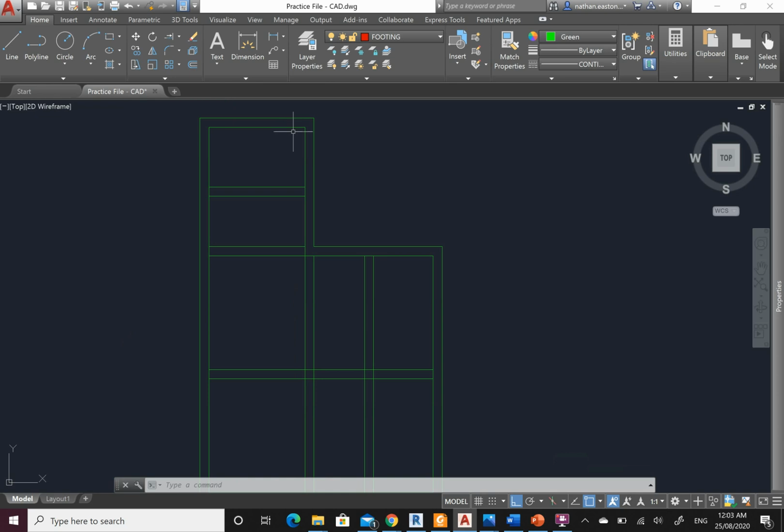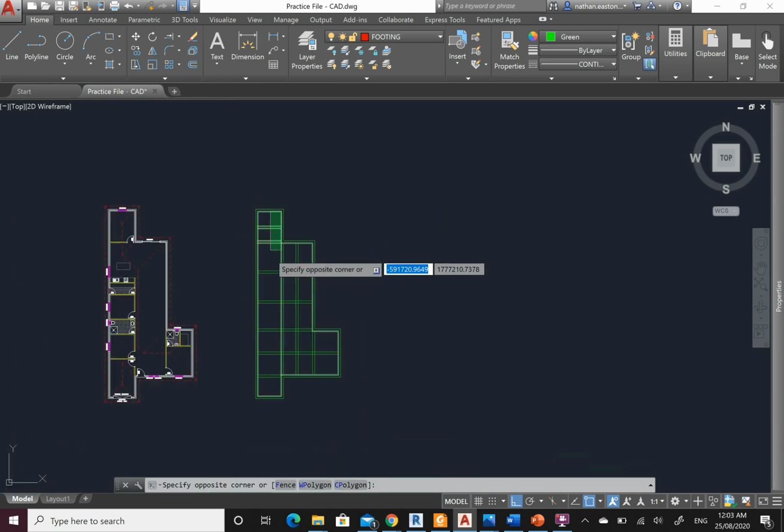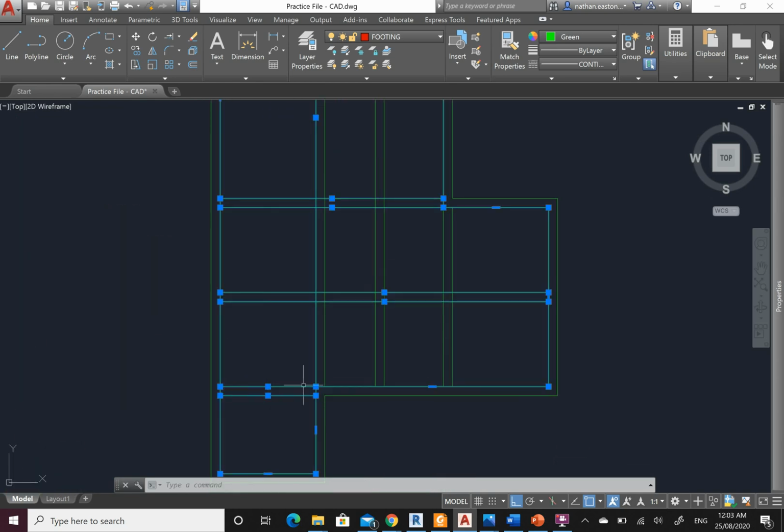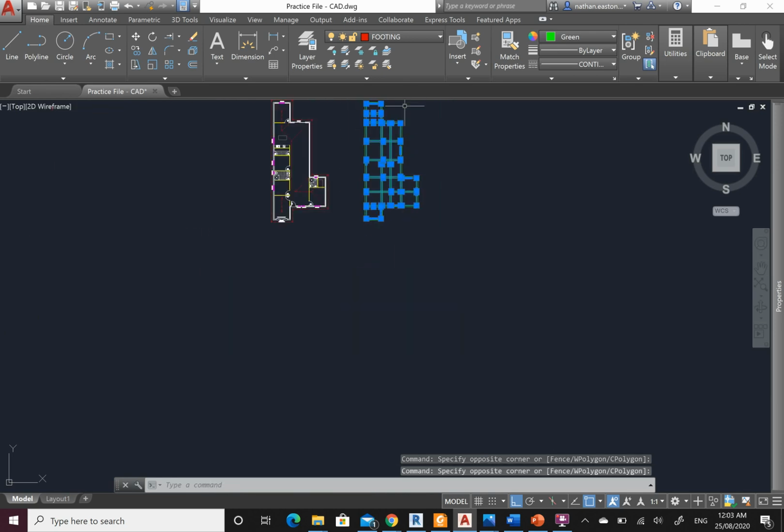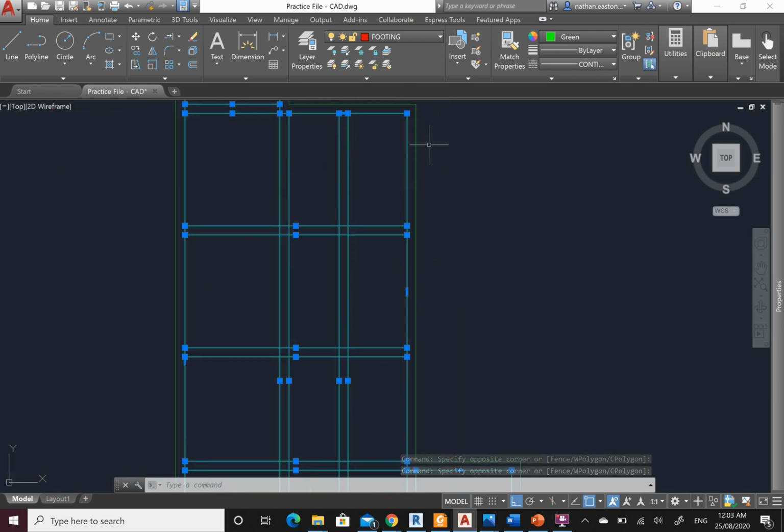Now let's come through and select all of the internal lines. Okay, so this external line we will see. If we look at our slab, we see this. We don't see these, there's concrete over them. So what do we do with any kind of beams or lines that we can't see? Well, we make them dashed.